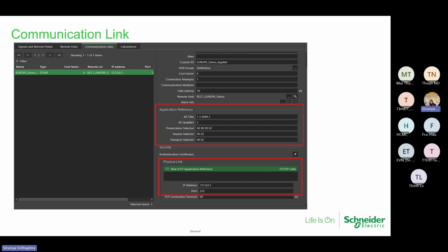And then individual devices which are not connected to anywhere, right? So we can connect to them with IEC 104, like this. We're going to be the client, right? They're going to be the server, because they will provide points. So this one they can provide one link, and I think you were saying maybe you can put two links, but I think one link should be fine. You probably don't need two links. You can double check and discuss with the other guys, one or two links.